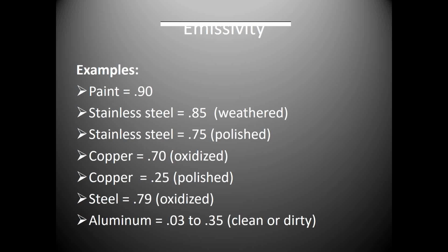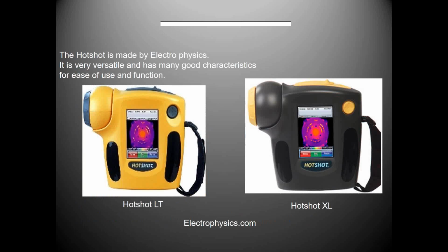So this is just one of the things with thermography, where if you want accurate temperatures, you need to set it up properly. If you just want to see temperature change looking through the screen, then all the cameras will work just fine. But again, I remember the first camera that I quoted for the company I worked for back in the mid-90s was $65,000. So there was no chance that my company was going to buy a $65,000 camera. So we used outside services.